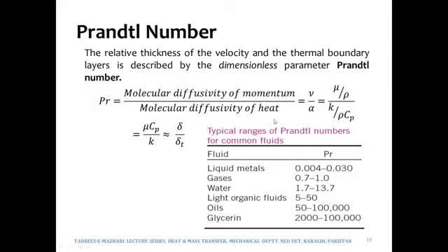And the heat diffusivity is in fact represented with an alpha, and we had discussed the heat diffusivity for the very first time in the first chapter, where alpha was k over rho c, and this momentum diffusivity or this kinematic viscosity is a ratio of the viscosity to the density. So the density will get cancelled out, and we will be left with mu times c over k.